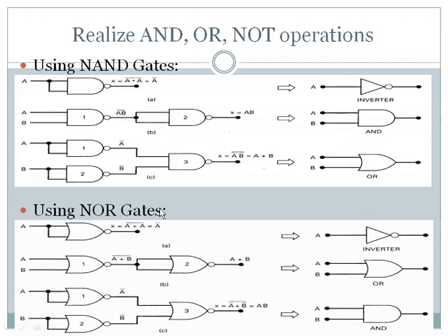You can see that the output is the inverse or complement of the input, so the NOR gate, when both the inputs are the same, performs the NOT operation. So I can say that the NOR gate connected in this way is equal to a NOT gate.